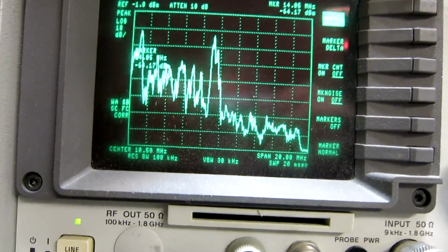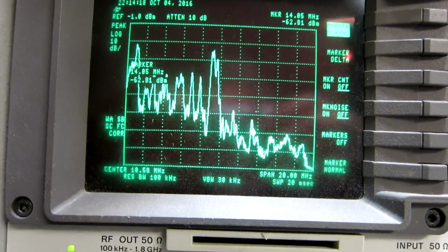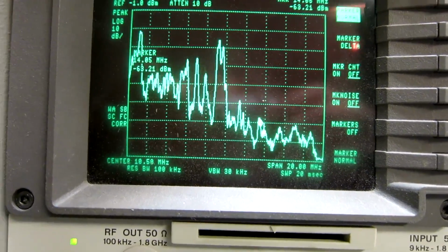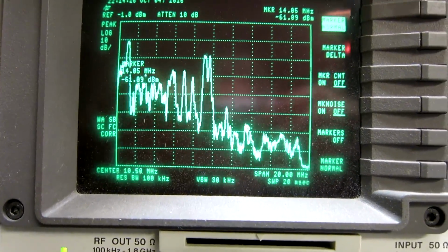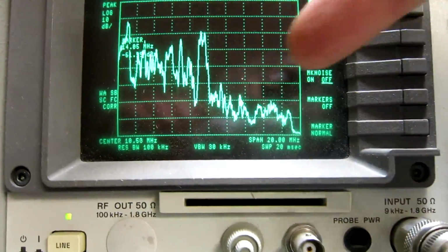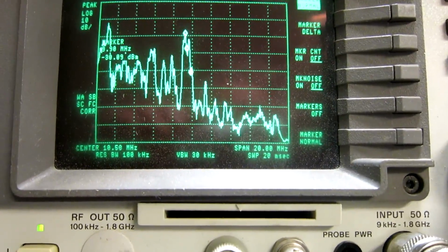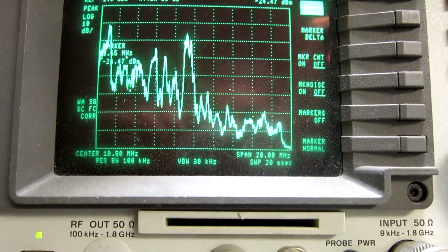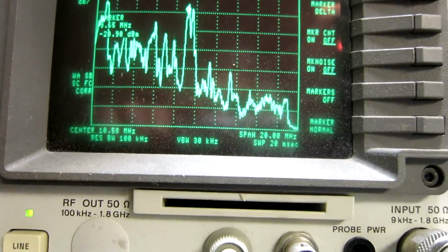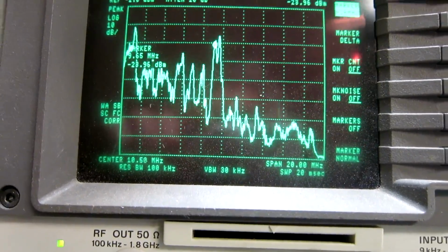I have connected an antenna now with a lot of amplification, and that is the strong signal that I send through the crystal notch filter. The time is 2:30 in the morning. There is nearly nothing at 14 megahertz, as you can see, but the strong signals here at 9.5 megahertz, and the level in the order of -20 dBm.